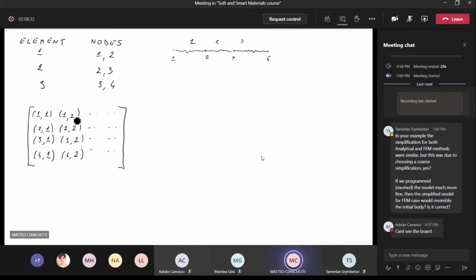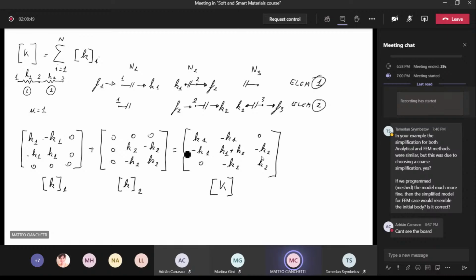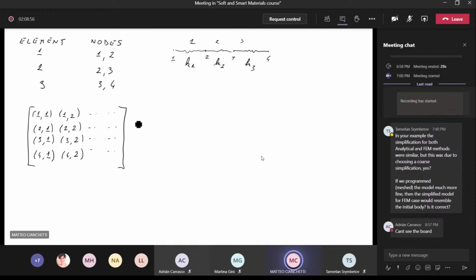So you can notice that actually the stiffness values K1, K2, and K3, also looking at the shape of the example that we saw before, appear in the stiffness matrix in row and column numbers matching the node numbers in the table.